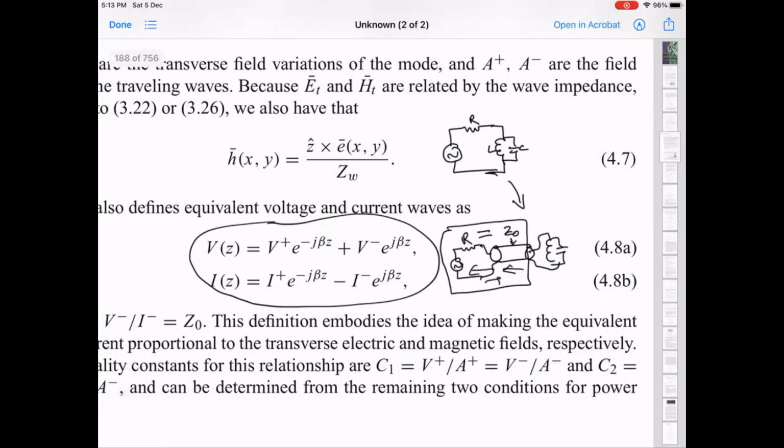measurement system is at room temperature, and there's a long cable, so this transmission line is not very small, and then at the end you have some device. But even if everything is at room temperature, you'll typically have some cable, and then there's a question of, okay, how do I figure out the waves which are going to the right and the left in this circuit? Of course, one can use the knowledge that if R and Z naught are the same, then really nothing is happening.